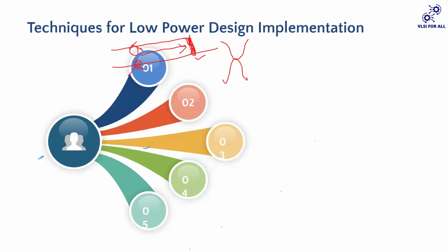But when you say positive edge triggered, negative edge triggered, what is actually triggered? It is the voltage level changing from 0 to 1. At that event, your flop is actually passing your data, so the data is transparent.